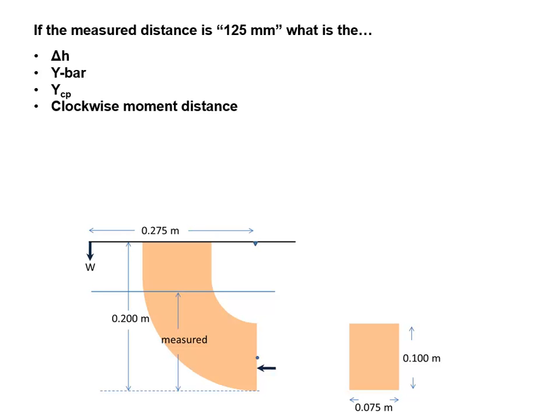So what that means is that we expect that the actual measured hydrostatic force is going to be some ratio of the moment distances, 0.275 meters divided by 0.1611 meters times 3.1883 newtons, and that gives us an equivalent force of 5.4425 newtons.